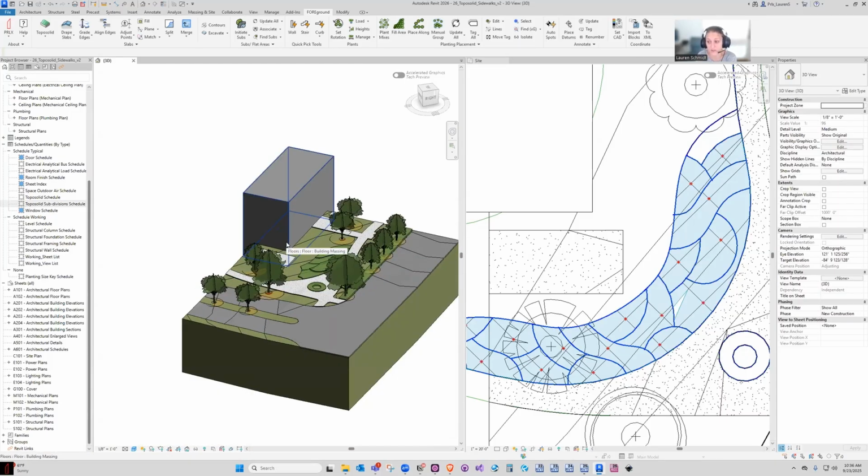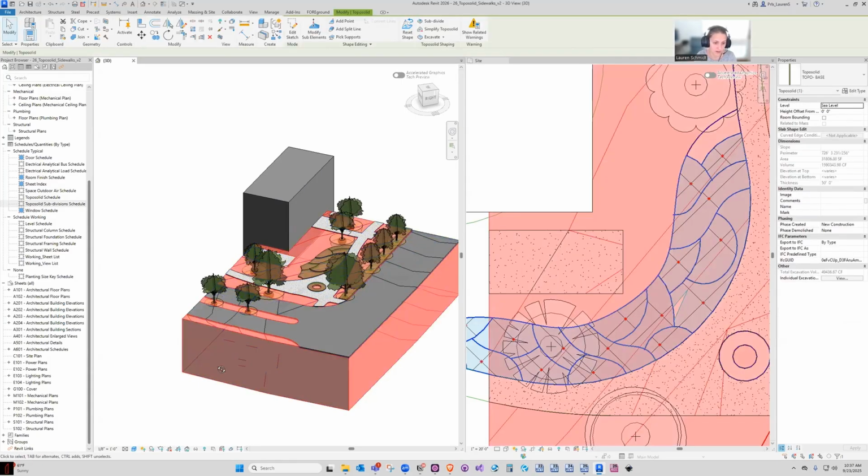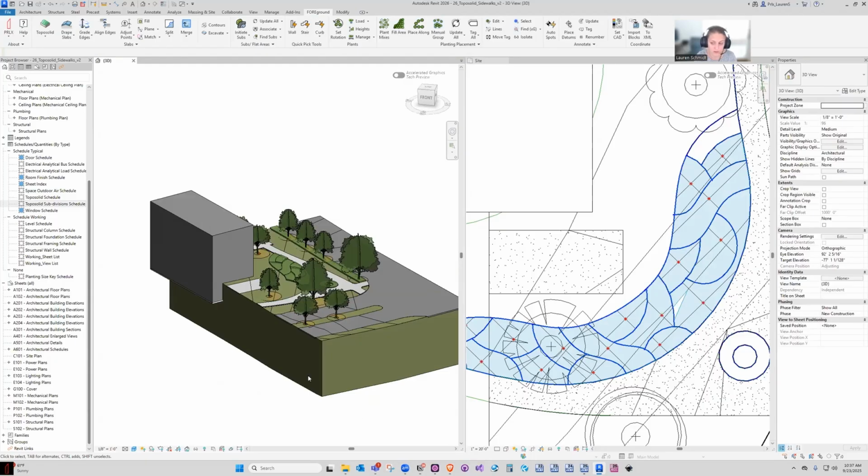You will also see, when you do lots of cutting and joining actions, particularly on a really big and complex topo solid, it can seriously impact your performance. So I would say use your excavations with caution and cutting in general with caution, particularly with large and more complex topo solids. And it's also good to be aware that when you're subdividing, it is going to be excavating it from your base. So if you do start to see performance issues, that also could be a reason.